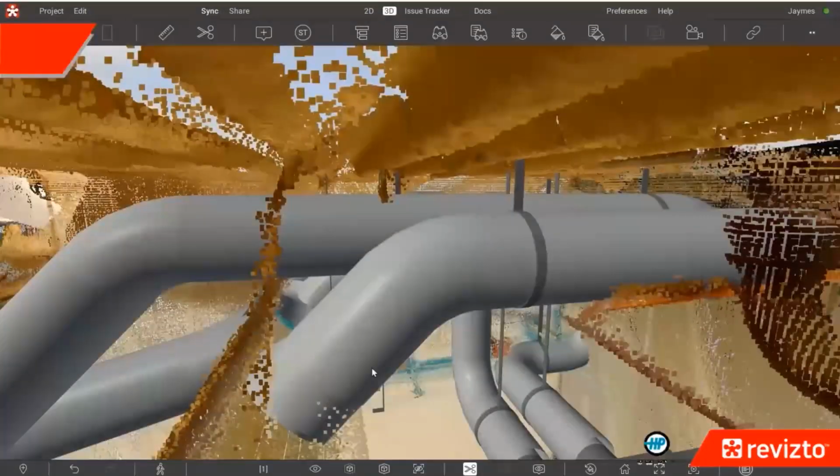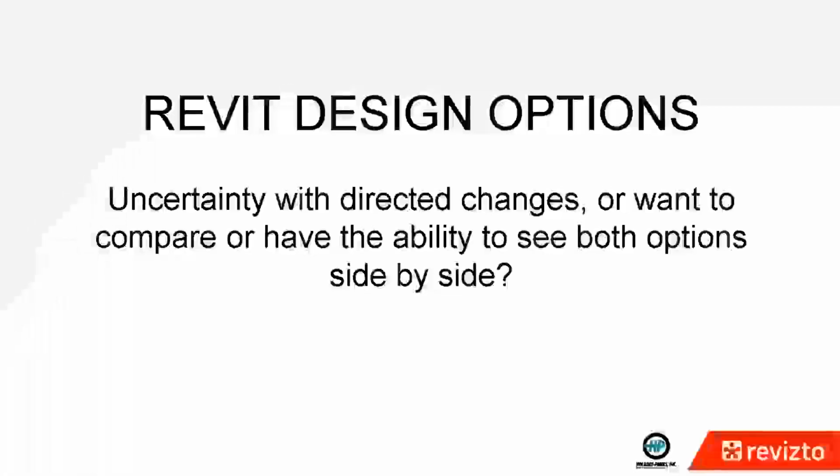In this particular instance, we're looking at some spiral round, knowing the existing conditions. That stuff's going to get ordered in 10-foot lengths and probably cut to fit in the field for some of that. Not all is sent out cut to length when you're tying into existing. So for these few taps in this area, the trunk line's there. It's close enough that they can make a field adjustment and make that work. So that's not anything that would require recoordination.